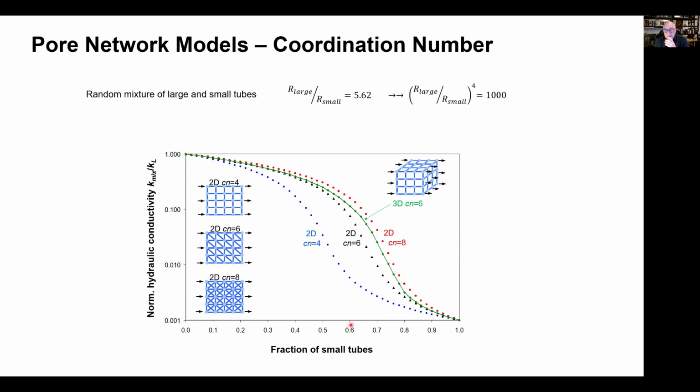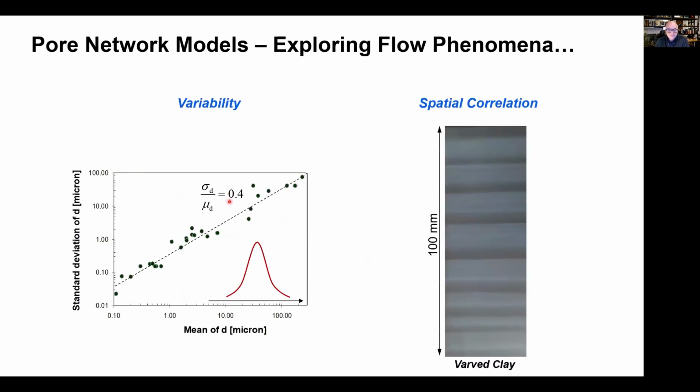And you see how these major breaks occur at different ranges depending on the connectivity. So be careful when you do pore network simulations. You may want to get the right 2D or 3D geometry and the proper connectivity. Connectivity 4, like in the simple cubic packing that we have described, is probably simplistic, even though it is very intuitive.